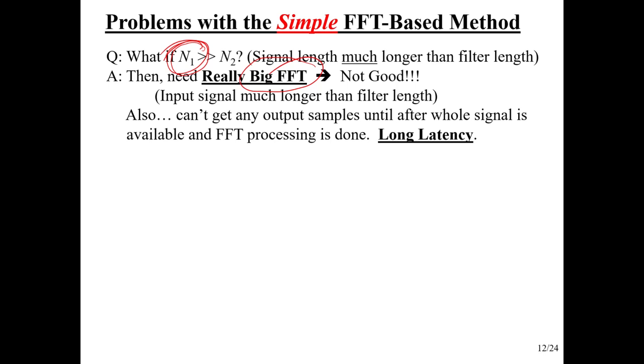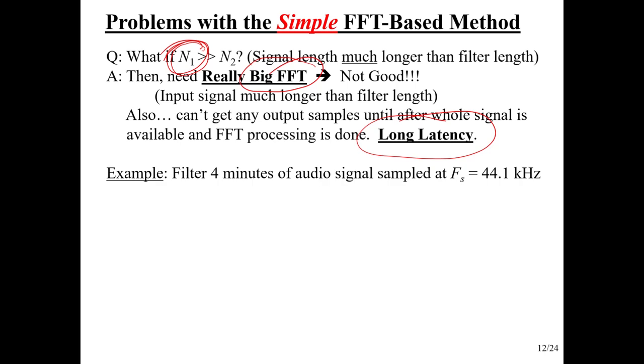If you want to filter a song that's 4 minutes long, you can't start doing anything until the song is over, and then you can compute your FFT and start putting the signal out. So very long latency. That's where the latency comes from in this algorithm: just waiting to get samples before we can start computing the FFT.